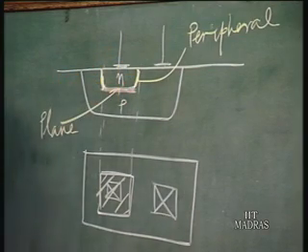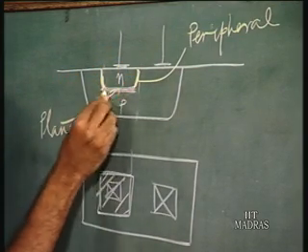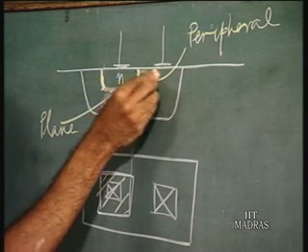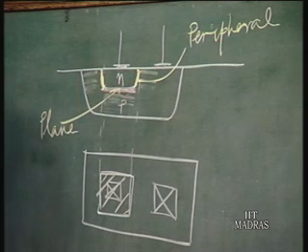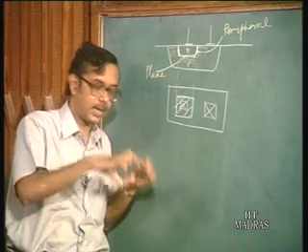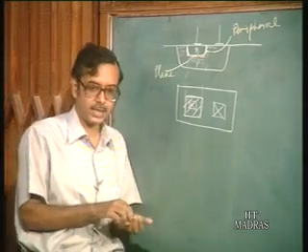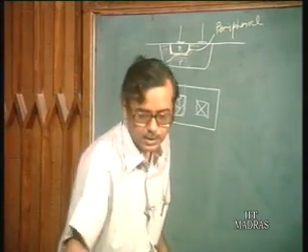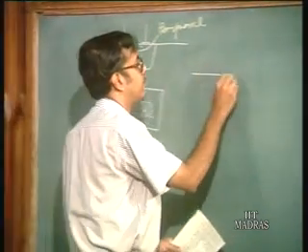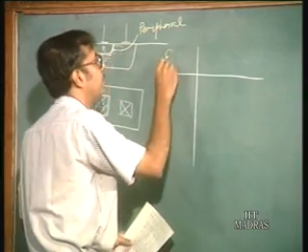So you have charge storage not only here, but also on the sides of this. So the capacitance is partly due to the plane region, and partly due to the peripheral region. I will just give you some data, and I think from this data certain points will become very clear.